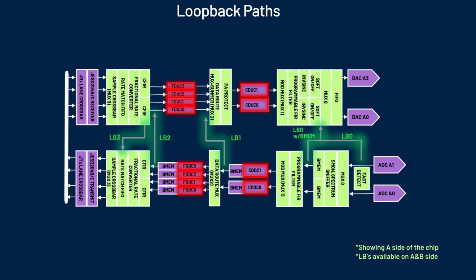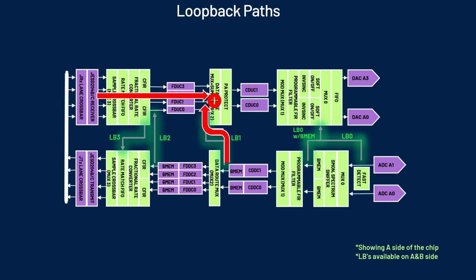To change signal frequency, utilize the coarse and fine NCOs. Set the frequency and the phase offset. Fast frequency hopping can be used to hop the NCO in the quickest time possible. Finally, blend the looped back data with transmit JESD data by using signal blending.